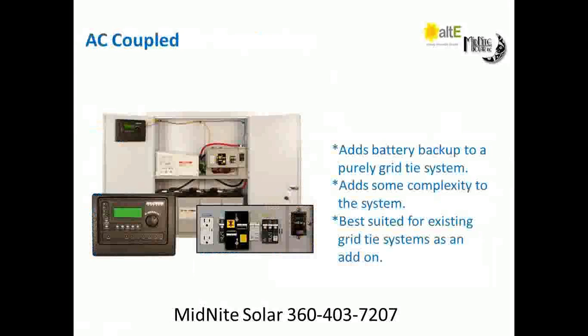It does add some level of complexity to the system. So in my opinion, it's best suited for an existing grid tie system as an add-on. There is an exception to that if you're wanting to power a whole village off-grid. SMA makes a very nice AC coupled setup where it does 3-stage charging and everything else. So if you're looking to do it as a village power system, AC coupled has some merit.